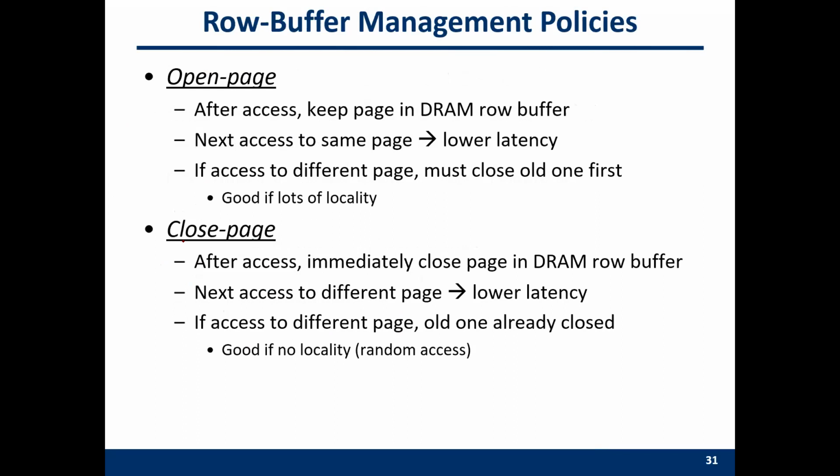Either you prefer that you may have a lot of hits, so after a read operation, you leave the row open. So you hope that next time you have another hit. Or you anticipate that you will have no hit, so you just close the row after each read operation. This is the difference.